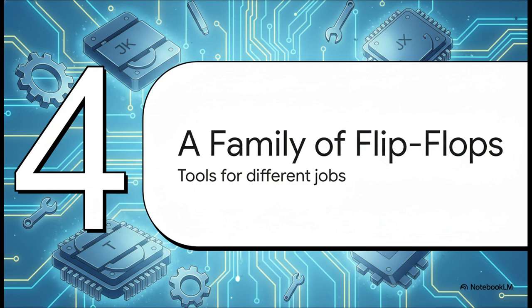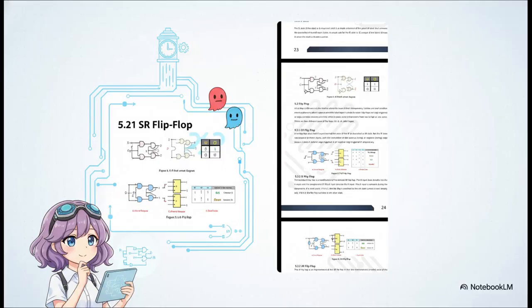So once this idea of the clocked edge-triggered flip-flop was nailed down, engineers just went to town with it. They developed a bunch of specialized versions, creating a whole toolkit of memory components, each with its own little personality. First up, the SR flip-flop. You can basically think of this as our old latch, but now it has a bouncer at the door, that clock input. It only listens to S and R when the clock says it's okay.